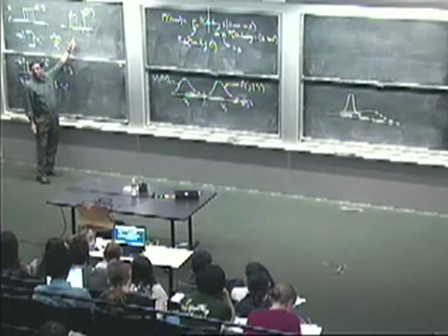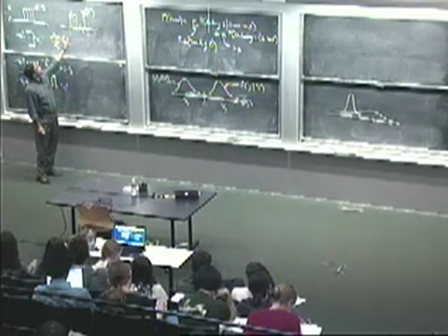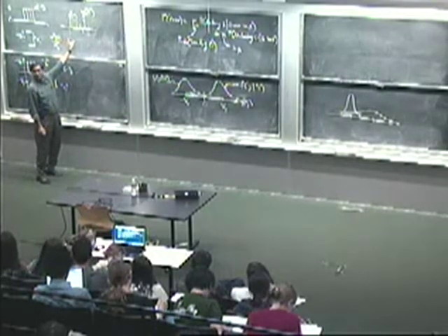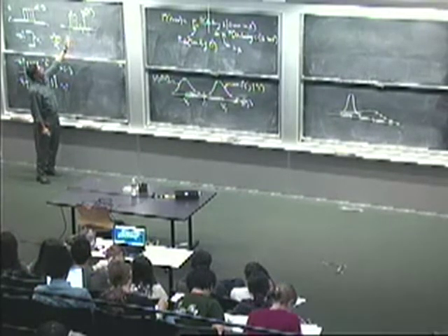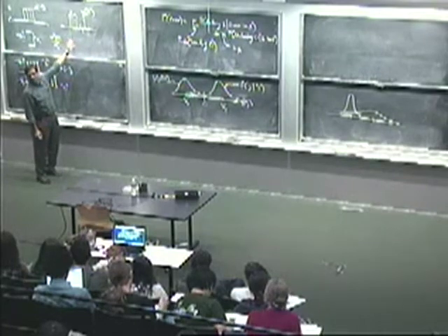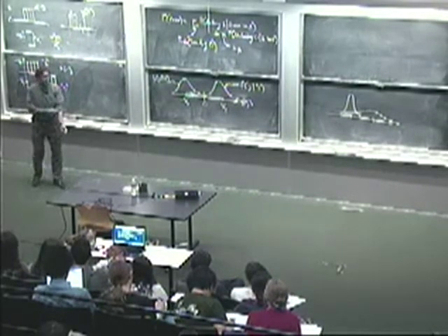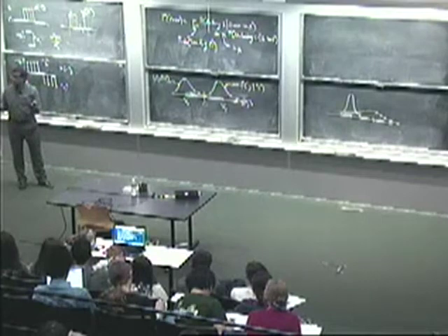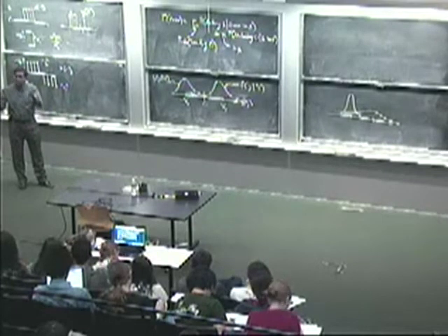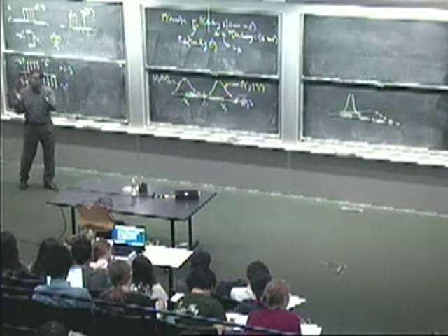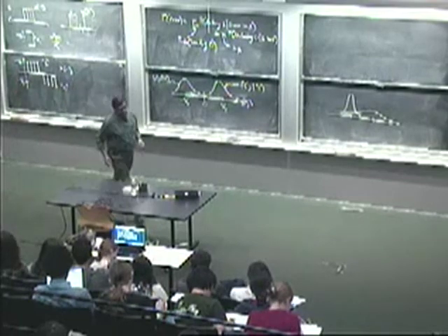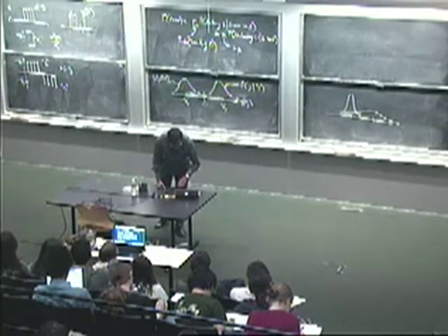This was a little bit arbitrary. It was conservative. Why you often do that is because the number of samples in a bit slot is small, and you don't want to get near the edges because you're a little worried about the transients. But if you've got enough samples in a bit slot, and the transients have kind of died out, then maybe you can just pick out a bigger chunk in the middle. And so that's what we're going to do here.